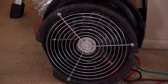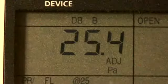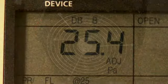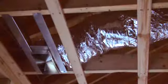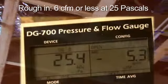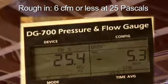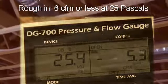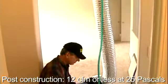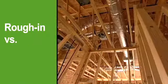You want to depressurize the ducts until the Channel A readout shows approximately 25 pascals. When conducting the test at rough-in, we're looking for a Channel B readout of 6 CFM or less. This represents total duct leakage at a 25 pascal pressure difference. If conducting the test after construction, we're looking for 12 CFM or less at 25 pascals.